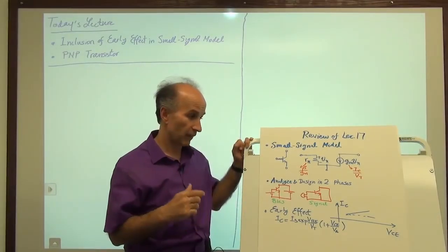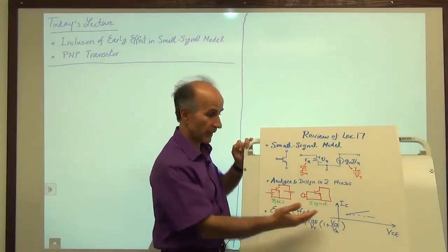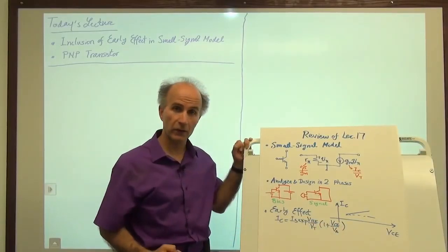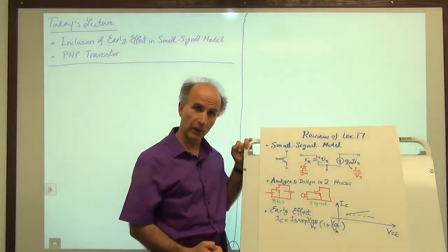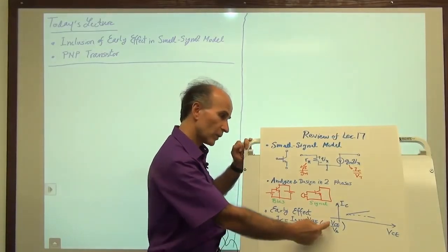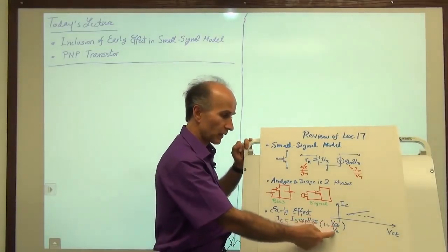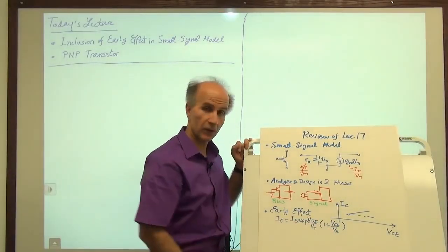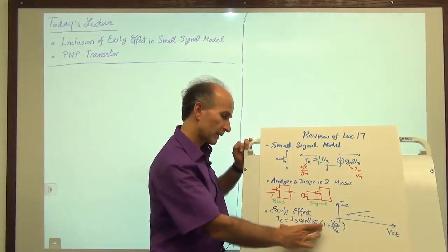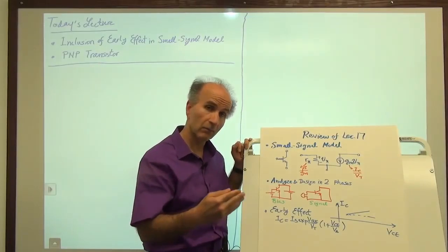And we saw that a very simple model to represent this increase is just a linear factor that is multiplied by our good old exponential. So we just say VCE, and then we have to get the units right, so we place some voltage here, which is called the early voltage. So that is, in a sense, the large signal model of the bipolar transistors.